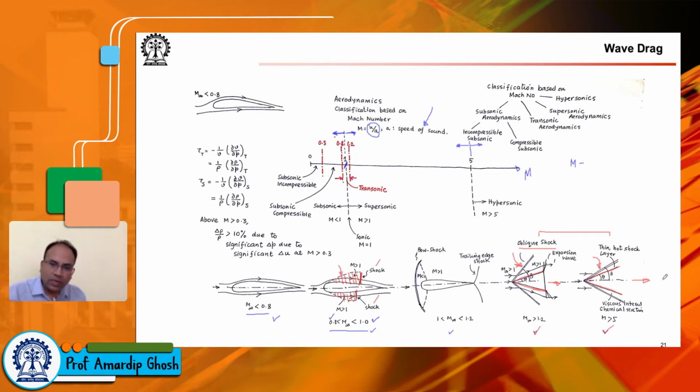So in the supersonic flow field, wave drag has some connotation, whereas in the subsonic flow field, now this is not just subsonic, it is subsonic, but it is close to that Mach 1. So close to Mach 1, local pockets of supersonic flow terminating in normal shocks, and these normal shocks create flow separation when they impinge on the boundary layer, and then an effect similar to pressure drag due to flow separation sets in, creating a very large increase in drag, and also in the coefficient of drag, or drag coefficient. And we will see these things in the subsequent slides.